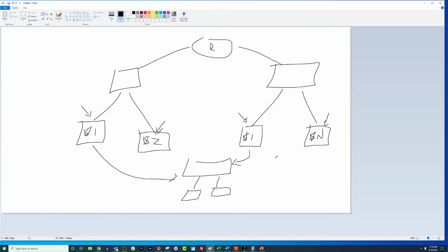But once you've established the Who-Is/I-Am and you've built your BACnet node list, an array of your BACnet nodes, then all of your read property, write property, etc., all of those services are going to use the BACnet virtual link and the NPDUs and APDUs to send unicast or multicast messages to BACnet devices.